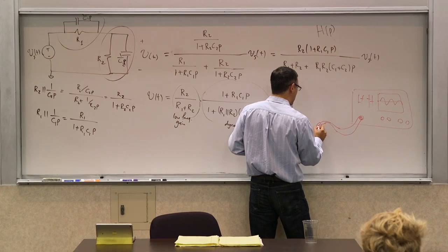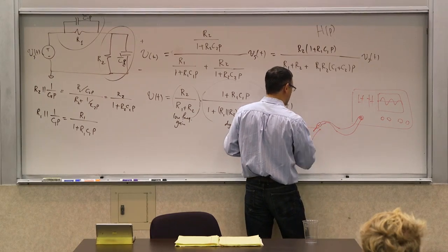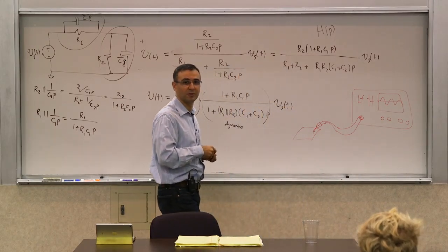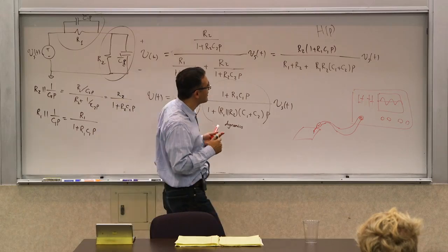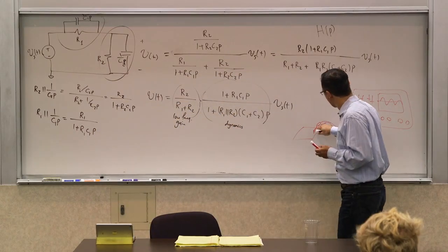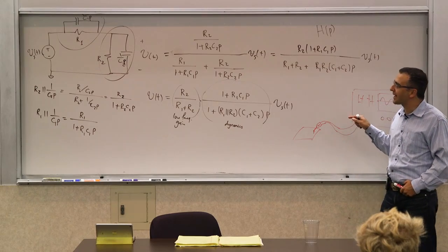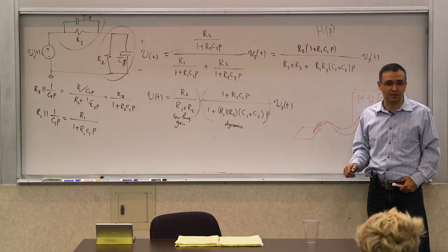There's a little switch here. There's a tip that you put on your board, or I don't know, whatever you have, your breadboard, etc., right? What happens is that is going to, so you're trying to sense this, right? You're trying to minimize the impact of what your oscilloscope does to your circuit.